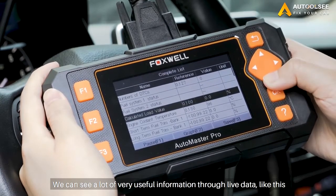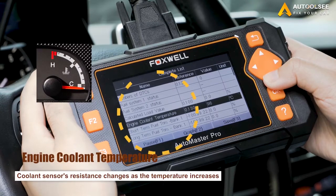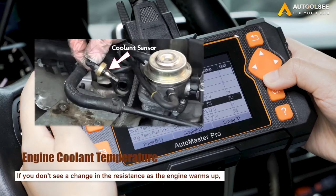Okay, we can see a lot of very useful information through live data, like this. Engine coolant temperature and coolant sensor resistance change as the temperature increases. If you don't see a change in the resistance as the engine warms up, or the resistance is out of specifications, the sensor is bad.